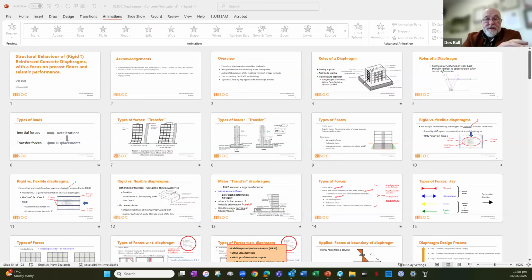So the crude method, which is the grillage and strut and tie method, says we just assume concrete's cracked. What that does is give you the maximum upper bound tension loads in your tension steel for your ties. So this is a way of bounding it. It's not a forensic tool. If you need to get down to that level, you need to get into the nonlinear finite element.